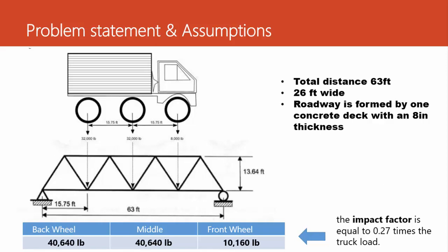At this stage, we assume that the steel truss members have a cross-section area of 20 square inches and are A36 structural steel members with a design safety factor of 1.5. The weight of each member will be assumed to be equally divided between the two joints at each end of the member. Notice that every longitudinal position of the truck will produce a different load distribution in each member. The bridge must then be checked for all possibilities.